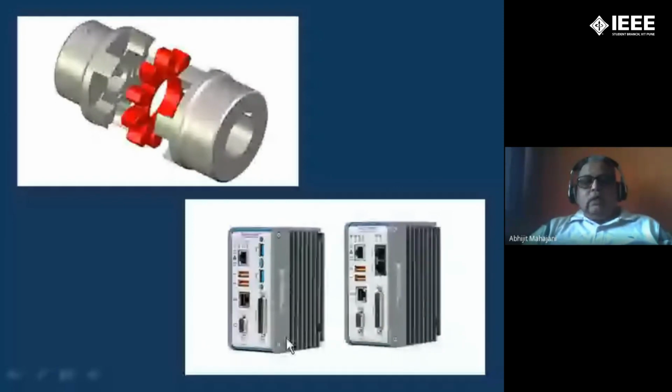Now you'll find that this edge node device will have multiple RJ45 ports here. One of the ports is a standard Ethernet port, the other port is a port configured for whatever protocol your CNC machine has got, and that protocol is fed here. And then they start communicating with each other. The data from CNC is collected and given to IT. Schedules from IT come through this, and they're probably given to the machine for starting and stopping and those kinds of things.